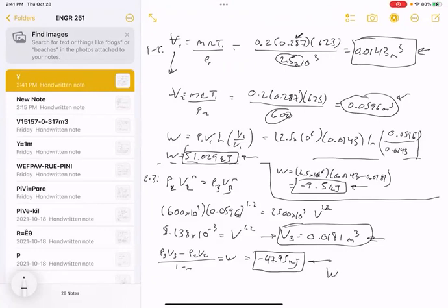So we'll say work net is equal to 51.029 kilojoules, and it doesn't matter the order you add them up, obviously, minus 47.95 kilojoules, minus 9.5 kilojoules. And what we're getting is minus 6.421 kilojoules. Now this is the net work over the entire cycle.